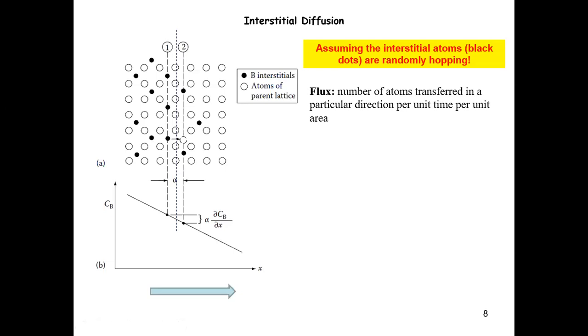Now, the diffusion that we're interested in is basically a transport of the atoms. Because the atoms are hopping around, you can take any atom, which at this time is located at this particular site, but at a later time can hop into any of the possible pockets available to it. Now, consider that this is a three-dimensional lattice and we have a cubic system. How many different available paths can this particular interstitial atom have?